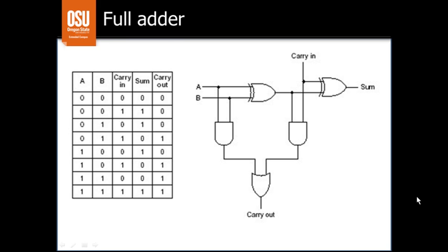Now we extend the half adder to be a full adder, which means that we have 3 inputs, that is, the bit from A and the corresponding bit from B, and a carry in that is provided by adding the lower order digits before we come into this.